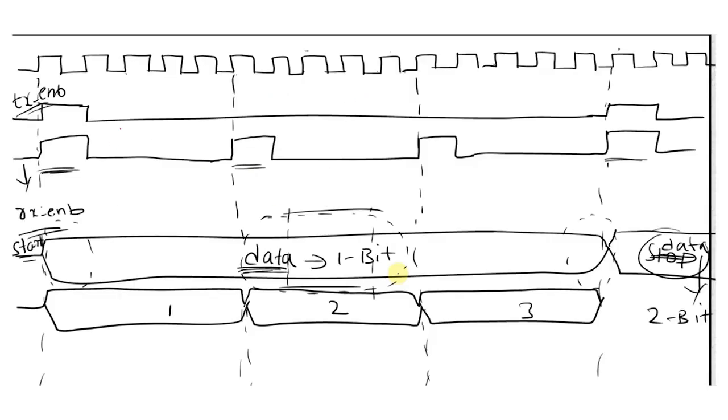So here what happens, there is a timing diagram. Transmit enable becomes 1. Transmit enable equal to 1 means after 6 cycles, 1 2 3 4 5 6, the receive enable becomes 1. Receive enable becomes 1, and it starts the data, and every 325 cycles one data bit will be received. So this is the timing diagram.